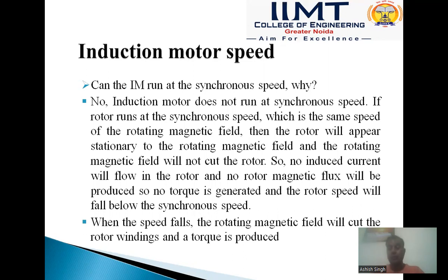As we know, the three-phase induction motor works on Faraday's law of mutual induction, and according to Lenz's law, the rotor rotates due to the relative speed between the rotating magnetic field and the stationary rotor conductor. So, coming to our question, can the induction motor run at synchronous speed?